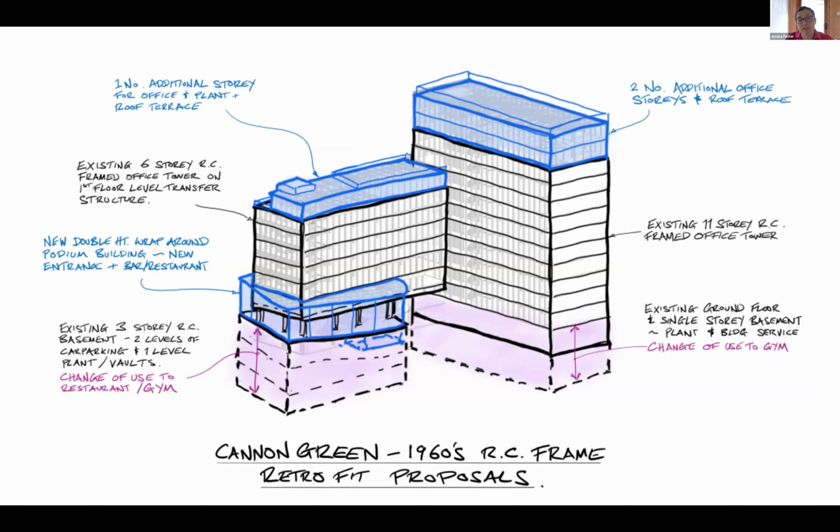And through that process of reviewing historic codes to see what loads would have been applied to the building at design stage, and the minimum steel requirements for reinforcement quantities and connections, because there was steel in this building as well, we carried out detailed load analysis of the whole building and were able to justify the existing structure with almost no additional strengthening.